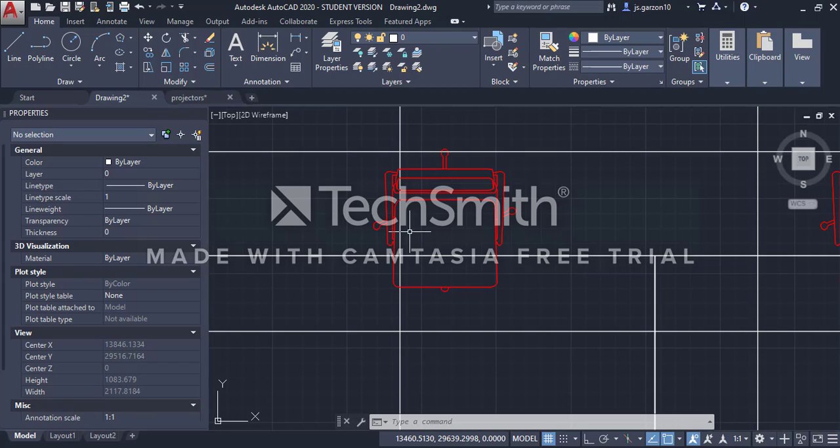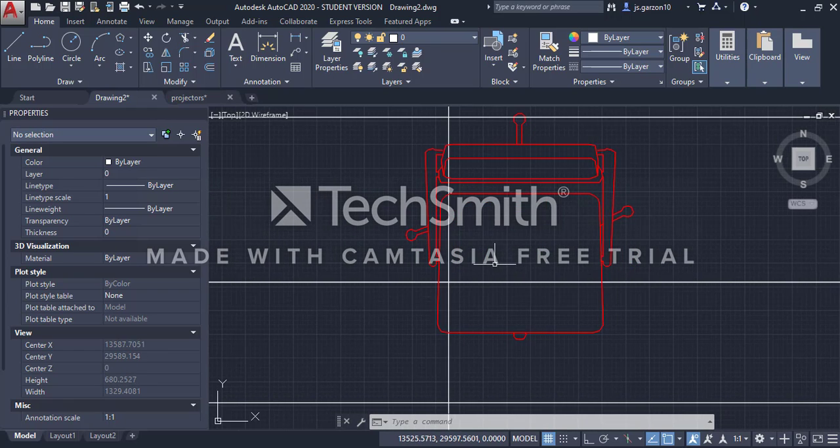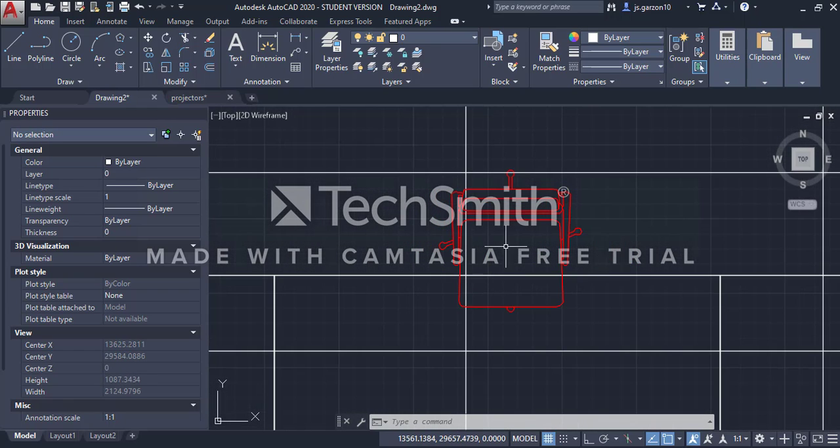So with this, a really useful option you can use to isolate the objects and to be cleaner in your drawings is to use blocks. What the block option does is take all the objects you select and group them, so that if you move one object of that element, it will move the whole group contained inside. So we are going to make a block with this chair.